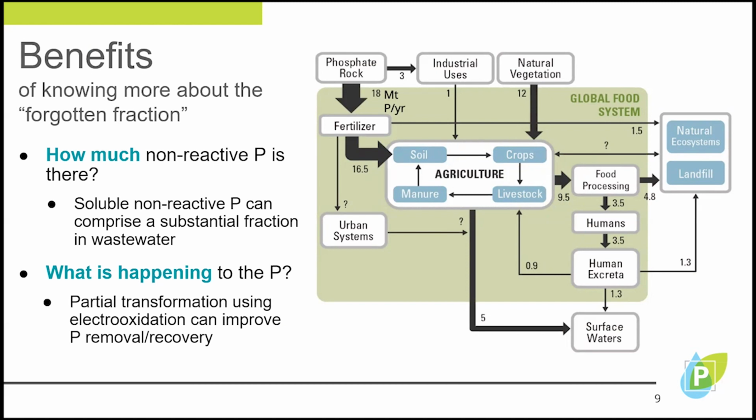Yeah, it's a good question. I think it's multifaceted. If we look at a traditional wastewater treatment like biological or enhanced biological phosphorus removal, it does a pretty great job. If you think about total phosphorus, the majority that it's tackling is that soluble reactive phosphorus form. So it does a good job against orthophosphate down to a certain level. When it comes to the non-reactive form, those processes tend to struggle a little bit more. It seems like it's the fraction that passes through, so it's more difficult to target. So in terms of efficacy, I think there is a difference there.